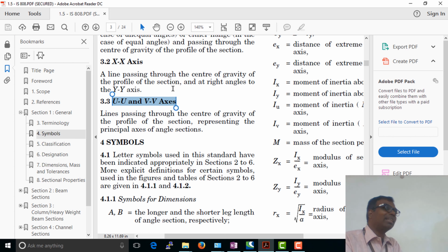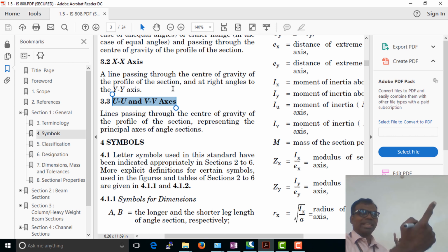You will be saying that this roof has members of 10 kg per meter run, and several such members make up the roof. So you just multiply it, and you can find out the weight of material which is required.